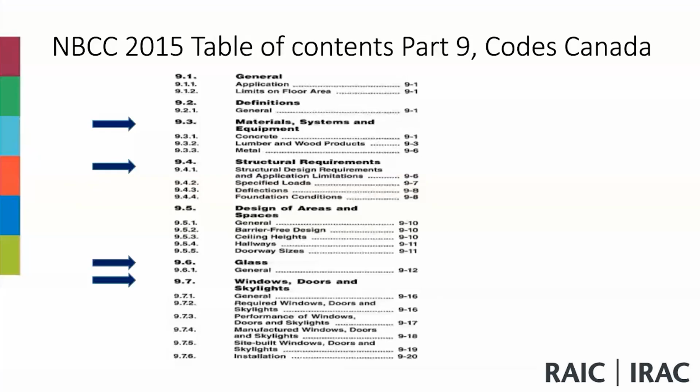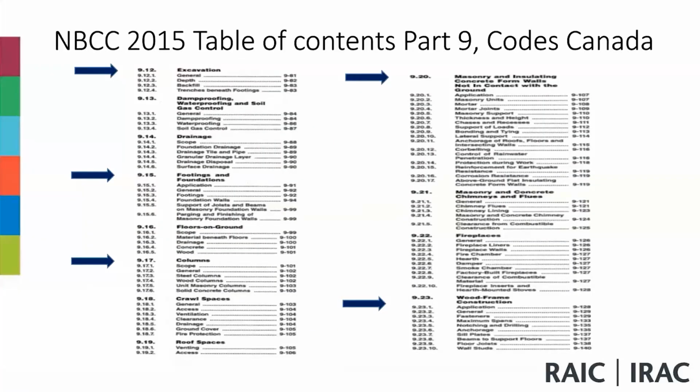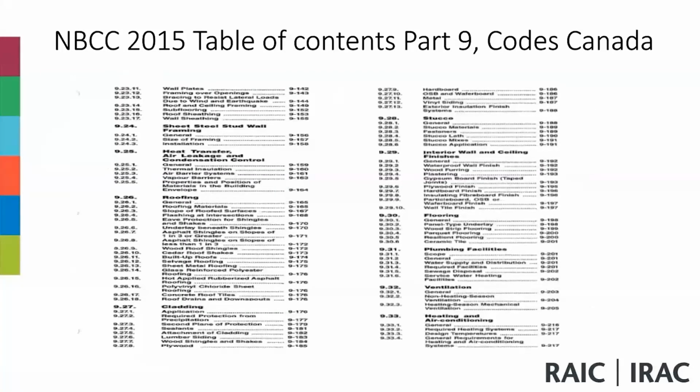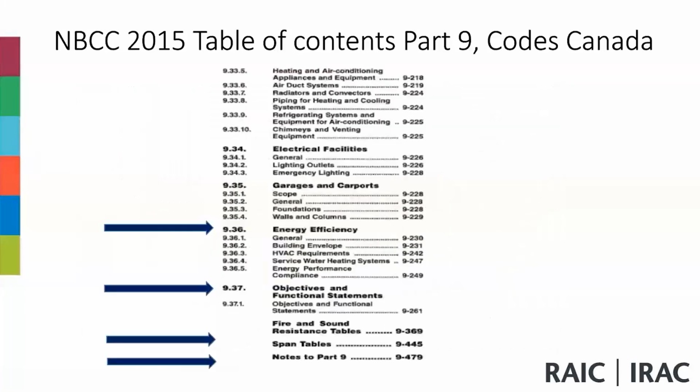We'll also be looking, when we're looking at energy efficiency, at windows, doors, and skylights. Structural provisions are also impacted by excavations, footings and foundations, columns, floors on ground, masonry, insulating concrete form walls, walls not in contact with the ground, wood frame construction, steel frame, and wood stud construction.